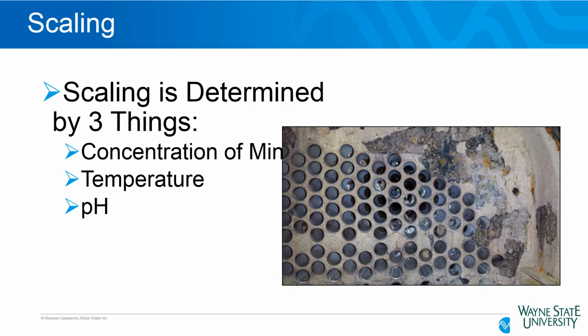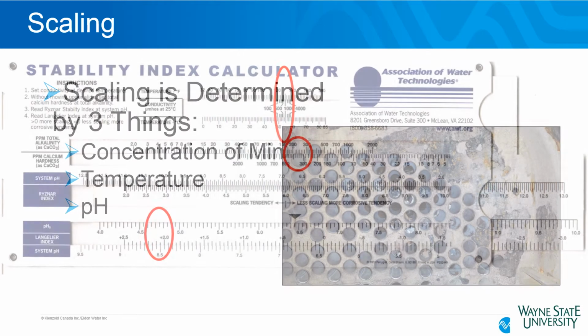For these HVAC systems, that is your condenser bundle. That is the hottest point in there. If you get really intense scaling, really oversaturation, you'll start to see scaling in your fill as well. And then pH. We don't do much for pH adjustment, but this is the theory behind acid feed. The more you lower your pH, the more it reduces the amount of scaling that can occur.